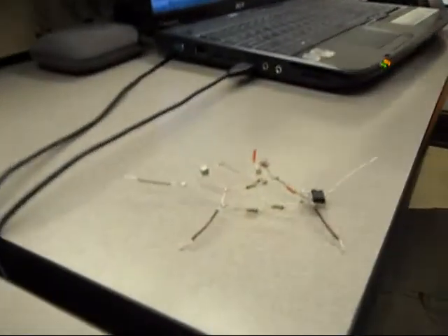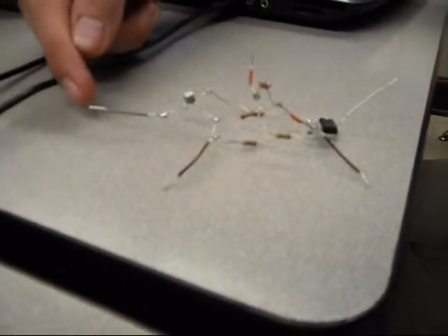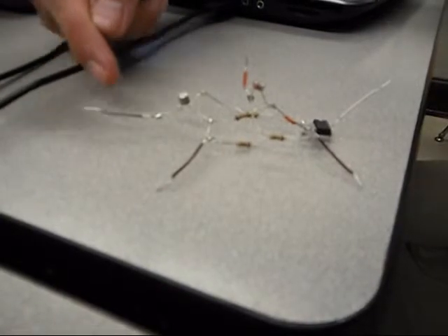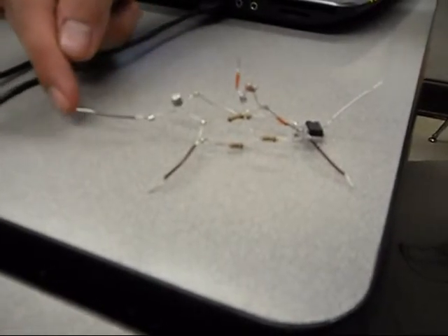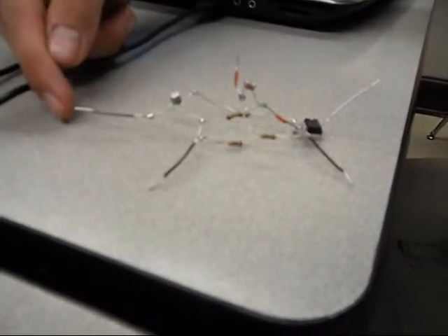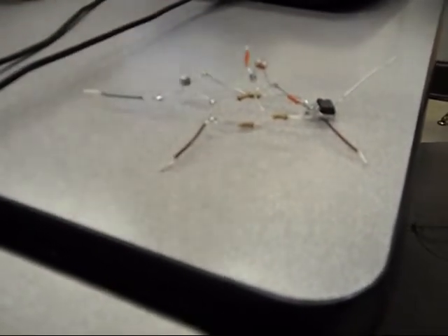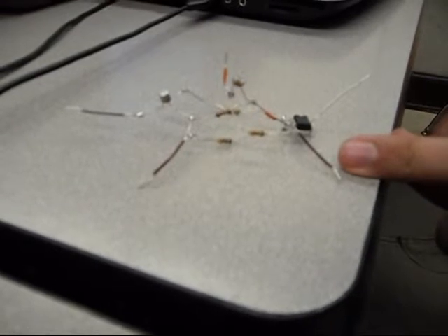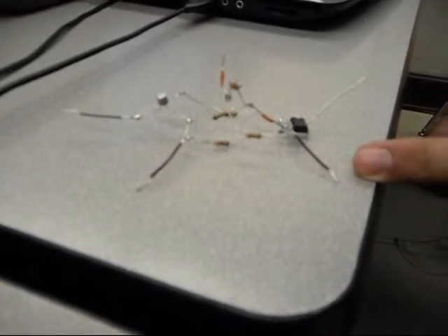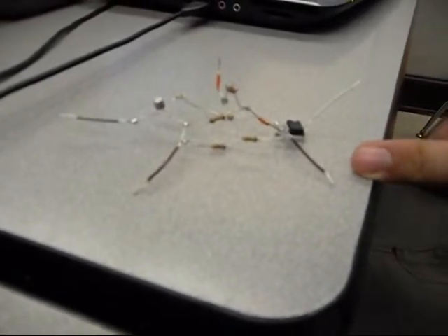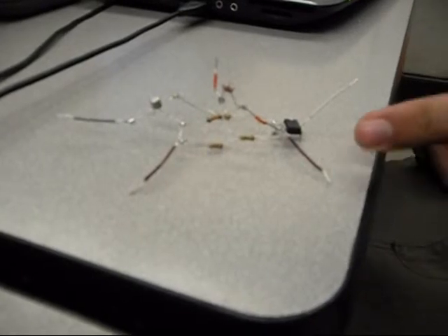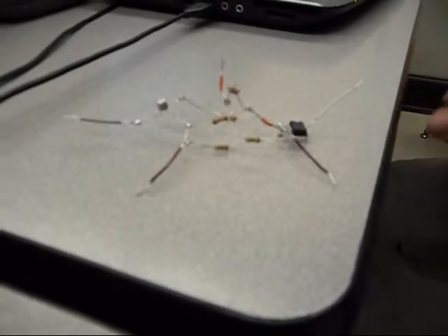Okay, this is what our final circuit is going to look like. Starting from the top, this gray wire is going to be coming from the collector. This is going to the negative end of our LED bulb. This maroon one is just a ground wire. This other maroon one is also ground. It's running to pin 4 of our op amp. In some op amps this will be a negative voltage, but here it's just going to ground.